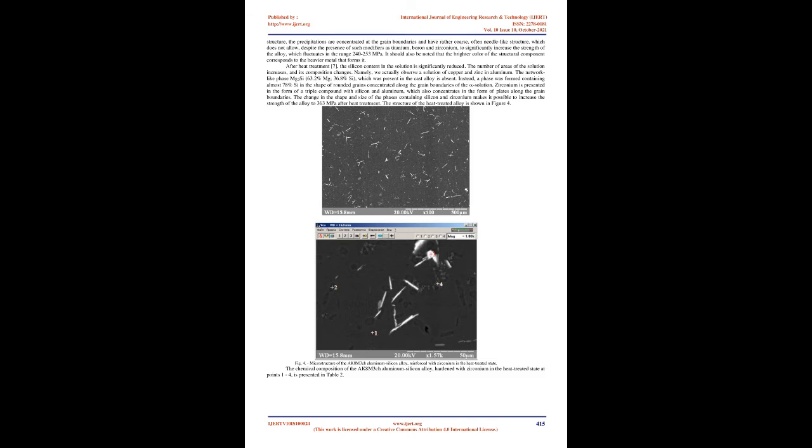The hardening effect of zirconium is partly explained by the formation of a refractory compound together with silicon, which can block the growth of the phase nuclei, which, in accordance with the classical modification theory, leads to the refinement of silicon. However, it remains unknown why zirconium grinds only eutectic silicon, and has a weak effect on primary silicon.